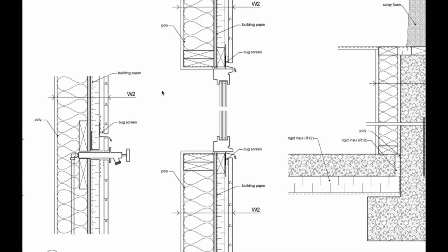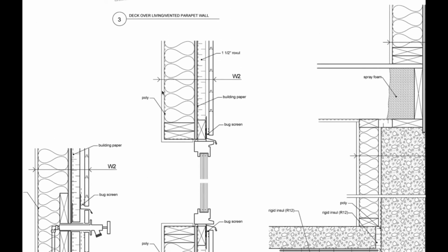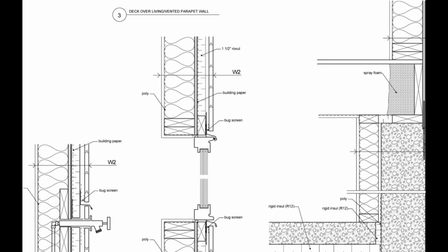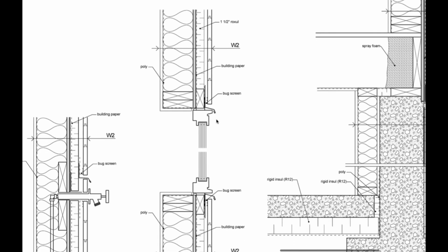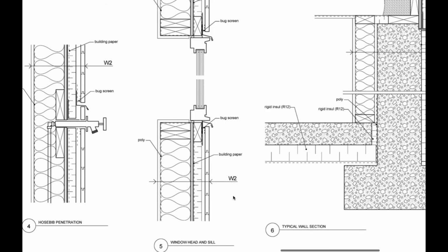Here's another elevation view of a window assembly. So same thing. They're doing the framed opening with the block on the outside and the flange, and then you have your tongue and groove siding on the outside. Piece of flashing comes in over top and underneath, which is good to know.